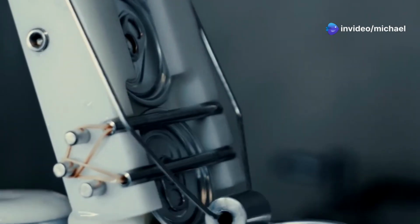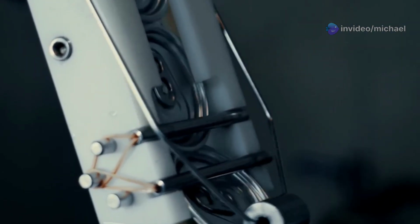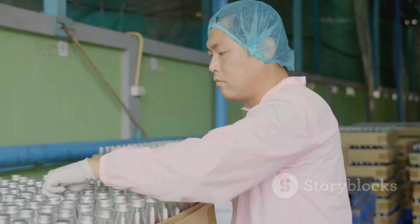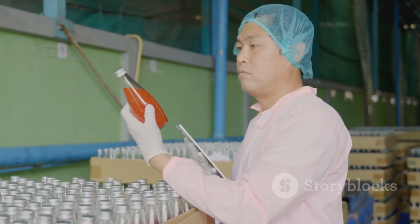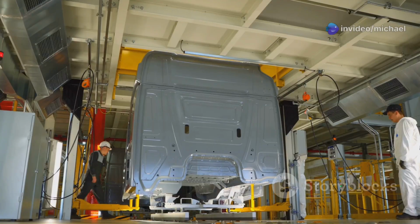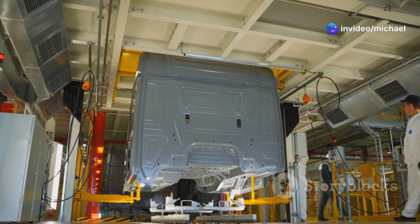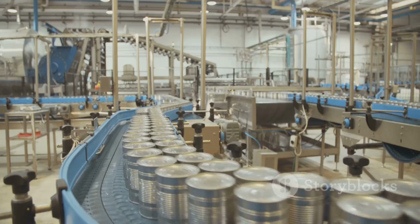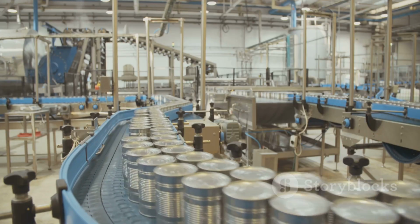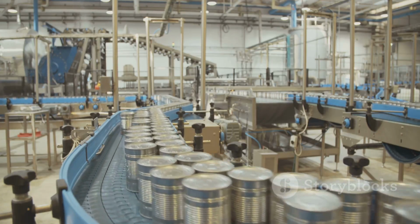Emphasize the use of appropriate tools and equipment to move cans, minimizing manual handling and the risk of accidental drops. Lastly, implementing robust quality control measures at each stage of production is vital. Visual inspections, automated scanning systems, and regular equipment checks can help identify and rectify issues promptly. By incorporating these preventative measures, manufacturers can significantly reduce the occurrence of can body dents, ensuring product quality and preserving consumer trust.